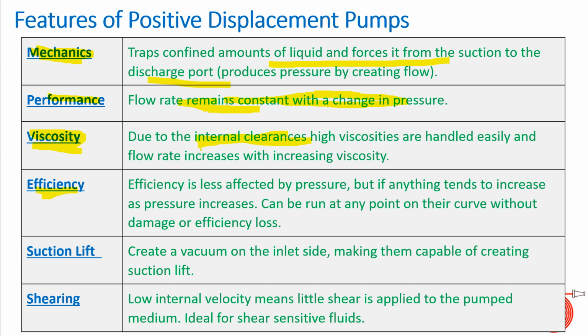Next is efficiency. If we talk about the efficiency of these pumps, it is less as compared to centrifugal pumps, and the maintenance cost is also very high, and also the person required for maintenance of positive displacement pumps needs to be good, highly skilled. So this is positive displacement pumps efficiency-wise.